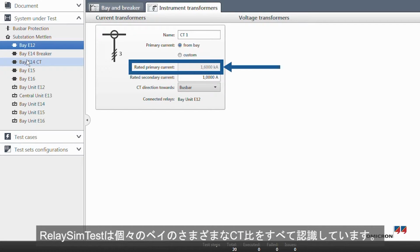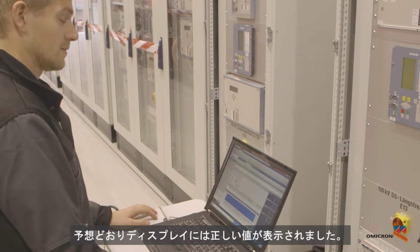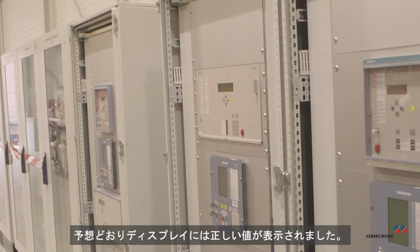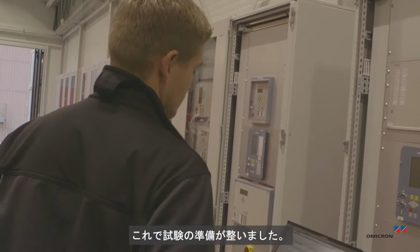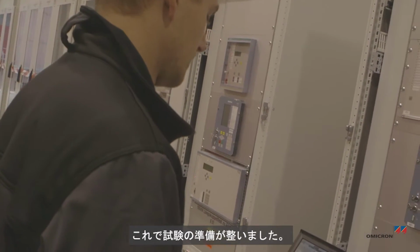RelaySimTest is aware of all the different CT ratios in the individual bays. As expected, the displays show the correct values. This confirms that the wiring has been done properly. Now they can start the test.